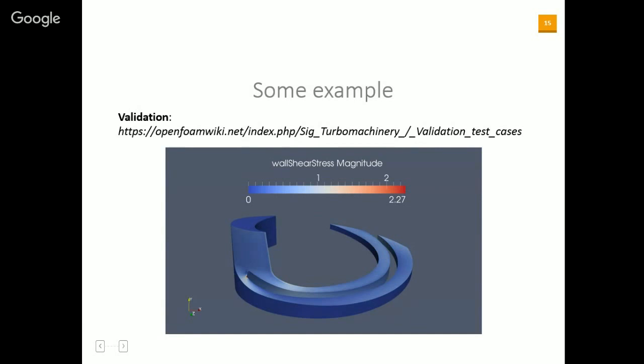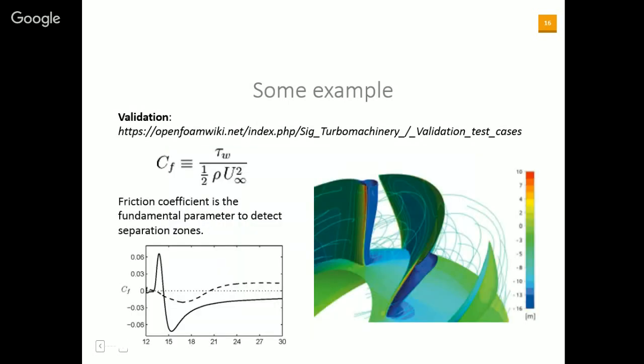In this slide, we are going to talk about wall shear stress, which is a parameter that defines the friction close to the wall, and this parameter is fundamental once again, since it's a way we can study the flow detachment from the wall. By flow detachment, I mean a phenomenon which separates the main flow from the walls and creates a lot of turbulence, in particular vortices.